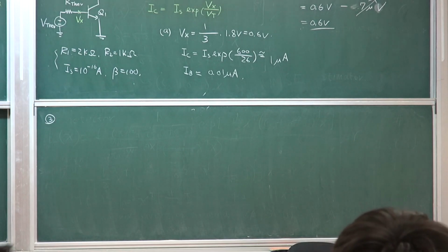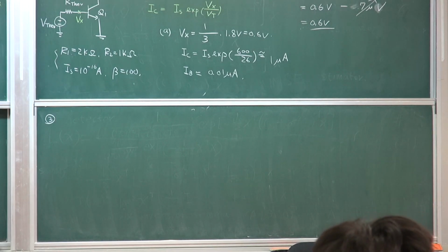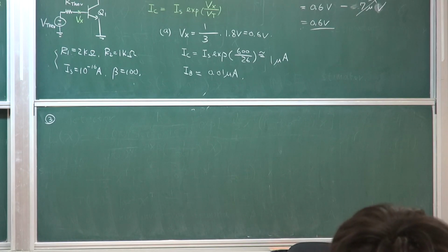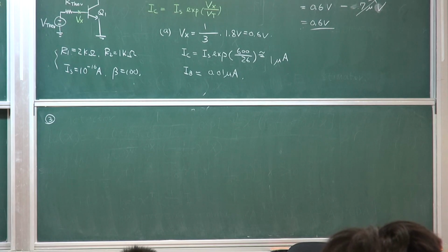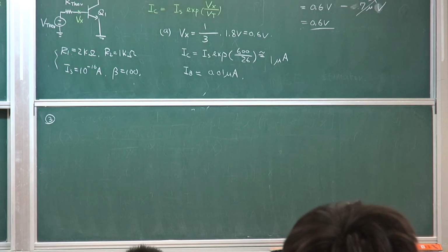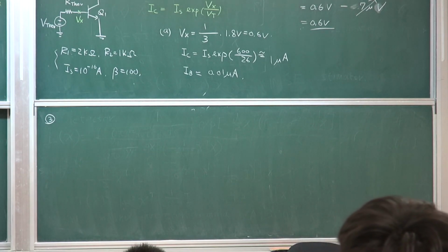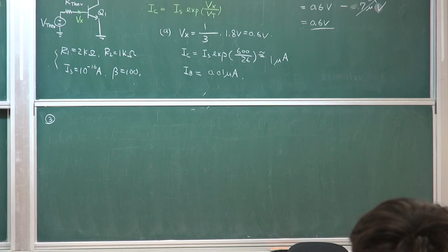So consider any variation in, for example, VCC. It's your supply voltage. Remember we talked about ripple voltage. If you have a supply voltage that comes in through ripple and a regulator, you can suppress it down to maybe 10% variation. So that accounts for maybe 0.2 volt variation.